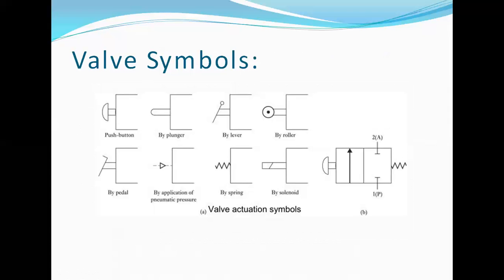And how the valve is being actuated, it is clearly specified, right? So this is called two ports, and positions is two. So here it is a 2 by 2 way controlled valve.